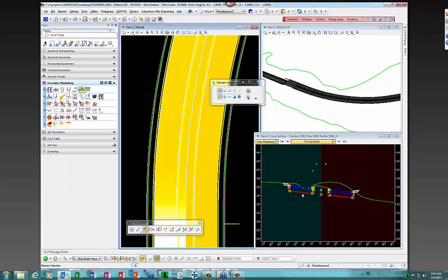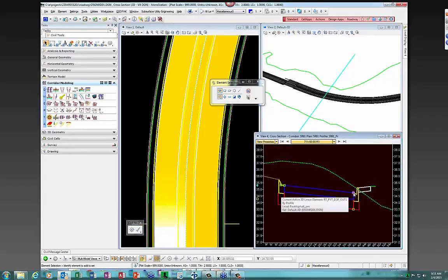And if you do that, then when you go to actually apply the super with the lanes configured the way they will, it will rotate about the inside of your curve. And it will rotate so that it holds this as your profile grade line, and essentially actually moves that pivot line up. Okay. And actually, this is not the actual profile grade line. It's actually this. It's actually sloped down from the profile grade line, if you will.